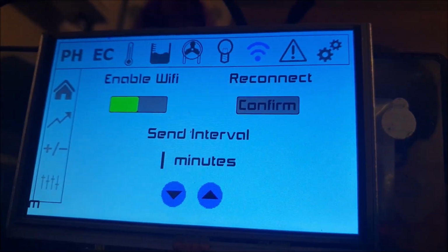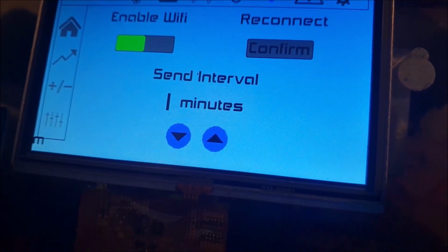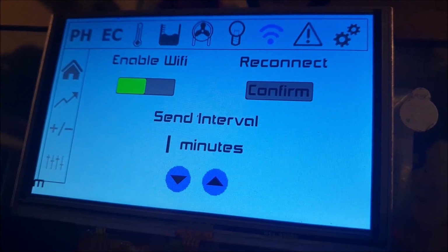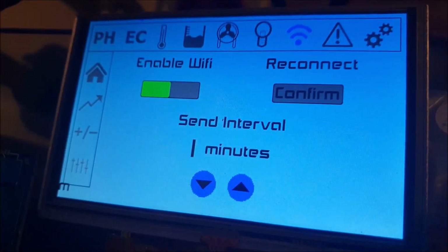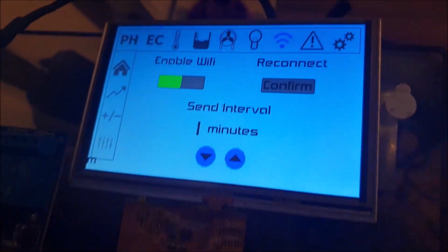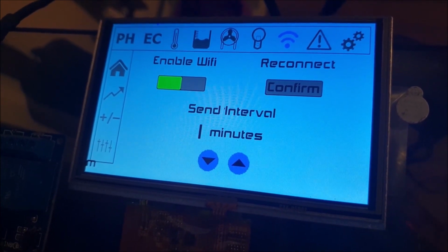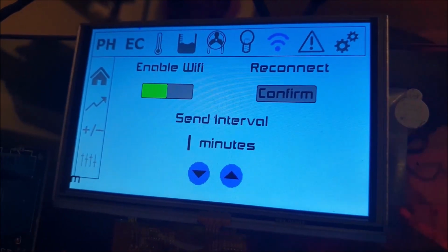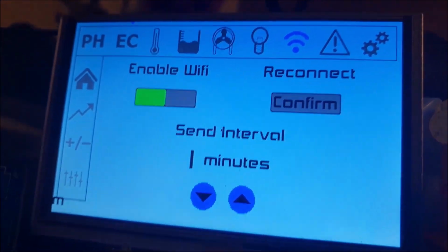So it has an array of 140 for each preset for the pH down, and another array of 140 for the pH up, and another array for the EC being 60, because we're going from a value of 0 to 6 max for the EC. And each time it doses the EC or pH, let's say in this case it's dosing the pH, it would take the current value and store it in that array.